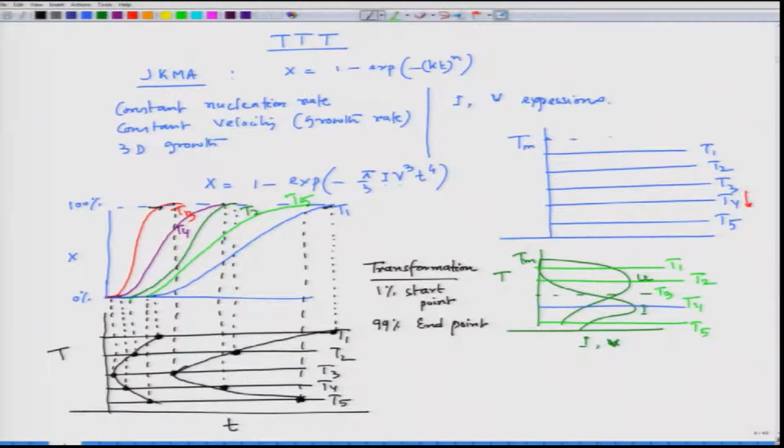So, now if you see, this is temperature and time, and it is taking a shape of C, which is also called the C curve, and since we are doing it at a constant temperature, which means we are following the isothermal mode of experiments, that is what it is called, isothermal C curve, also isothermal transformation curve, and this is popularly known as the TTT diagram.